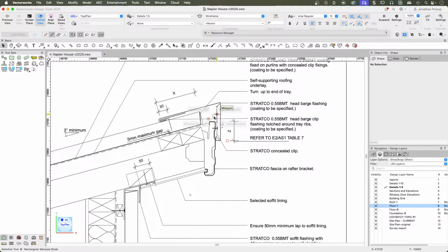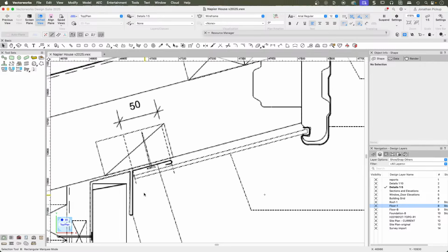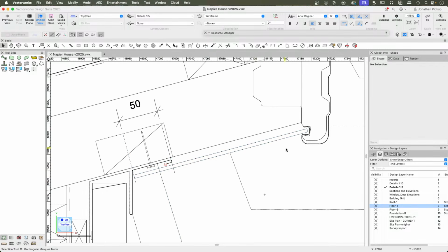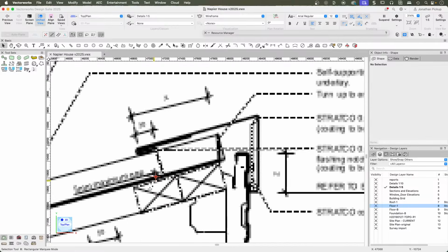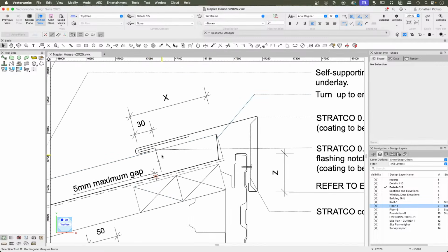Where possible, make sure you can deflect the water away. So for example, in this situation here, any water that gets blown up into this area will dribble down, the gravity will pull that down. This flashing here is then keeping that water away. It's deflecting the water out. If we have a look here, the water can't get into here because it's being deflected down the roof.